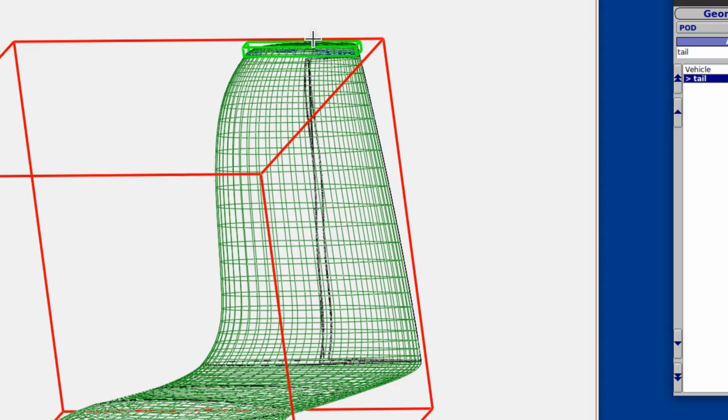The reason we need the load distribution along the span is that we can figure out how to handle the bending loads when the load is applied sideways onto this vertical tail. We're going to have a spar running down here in the vertical stabilizer, and we need to know how to build that spar to handle that load. Same sort of thing with the rudder. We'll probably have a spar in that, and we need to know that load along the span in order to build the spar to carry the load to the hinge points.